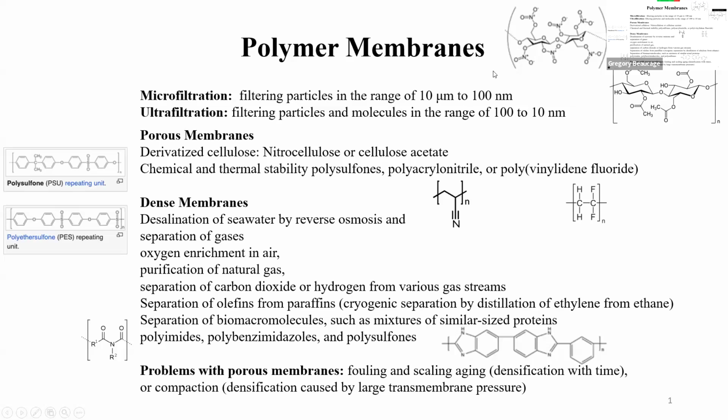Right. So they found out about thermal expansion and in fact thermal contraction, because in polymers you have this rubber elasticity issue. So the modulus goes with kT over the molecular weight. So if you raise T, the modulus, and the response to force, increases, so that actually the pores shrink when you heat it, because it's tensile, pulling it together, right?